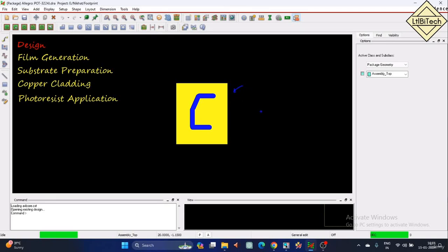I will take the printout of my routing and the solder pads which I have in the design, and place it on that copper cladding laminate, and then we'll expose it to UV or ultraviolet light. So the next procedure is the ultraviolet exposure.